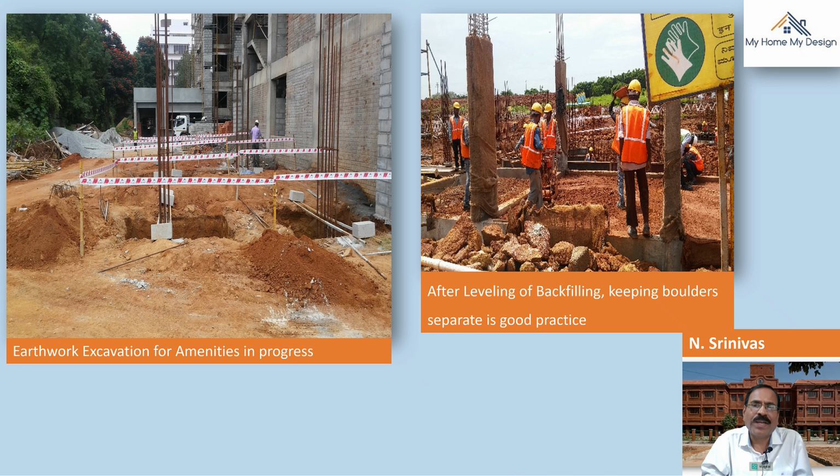The second photograph indicates after leveling of backfilling, keeping boulders separate is a good practice. So you remember very well that the maximum size of boulder or pebble allowed for the backfilling is 40 mm only. Precisely 37.5 mm, roughly it is 40 mm. 40 mm is only this much size. So the boulders which are more than 40 mm size, see here in the photographs, you can see the boulders are maybe 8 inches, 10 inches, 1 foot boulders, all kept separately. So they are not mixed for the backfilling. This is the scientific and engineering method that we are following here.